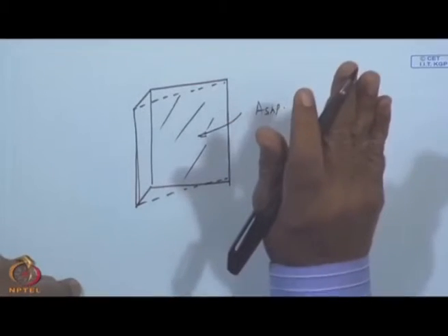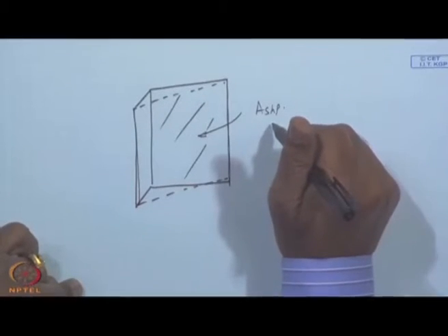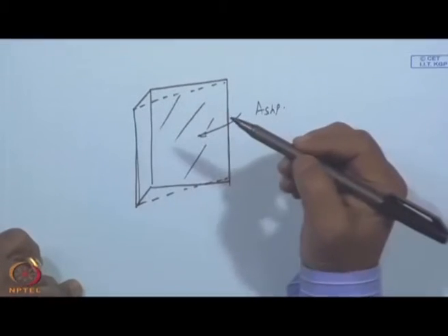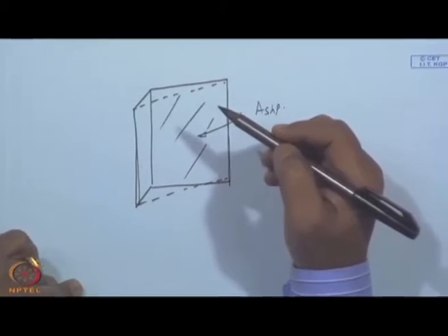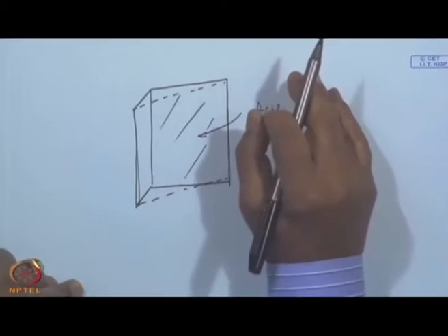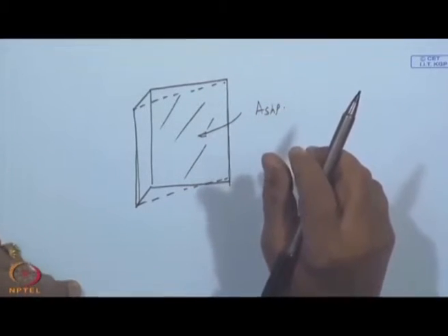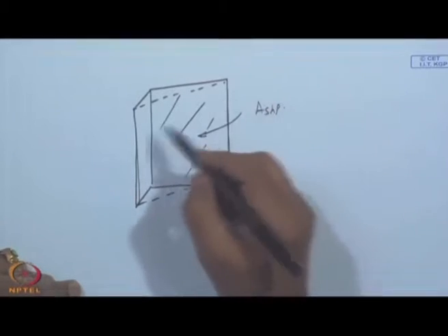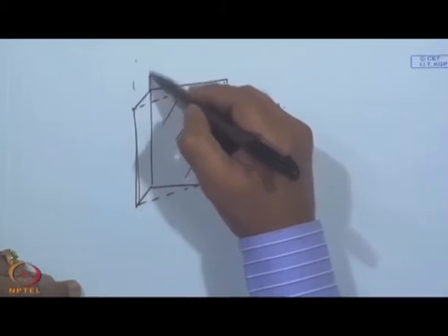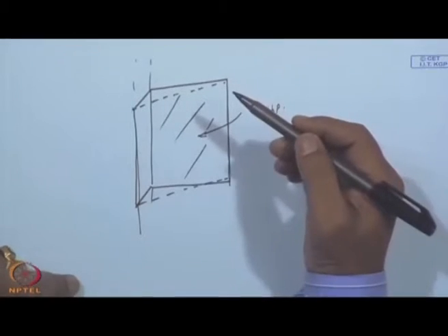Now, you do exactly the same way we have done and calculate the solar radiation falling on the shading plane as formed the way I have described. You will get the radiation received by the window per unit area of the window, introducing Fi for the shading plane. Now, of course, this also has got limitations in the sense this is pretty long, so that the shape of this is always a rectangle. Okay.